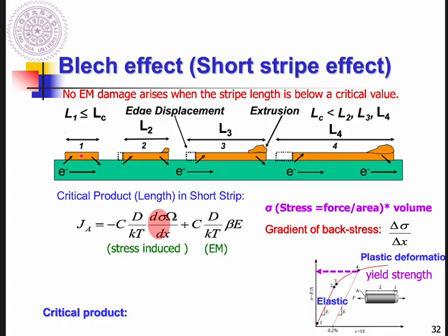But the ideal situation is that we don't want to have atomic flux, right? Because as long as you have it, you will see extrusion and void formation. So this should equal 0. When it reaches quasi steady state, we hope this equals 0, so we can find LC. So this equals 0, and you move this term to the right-handed side, so I can get the critical product.